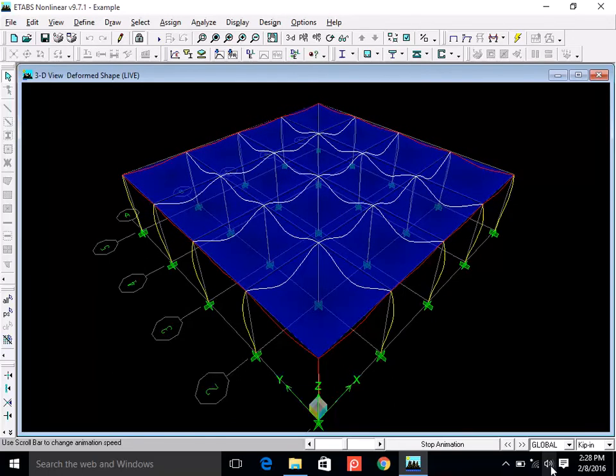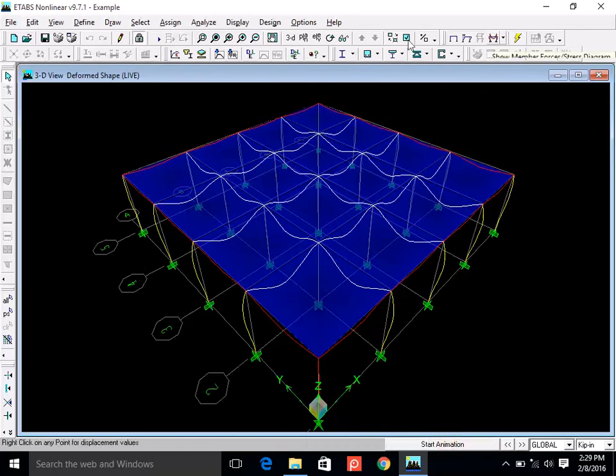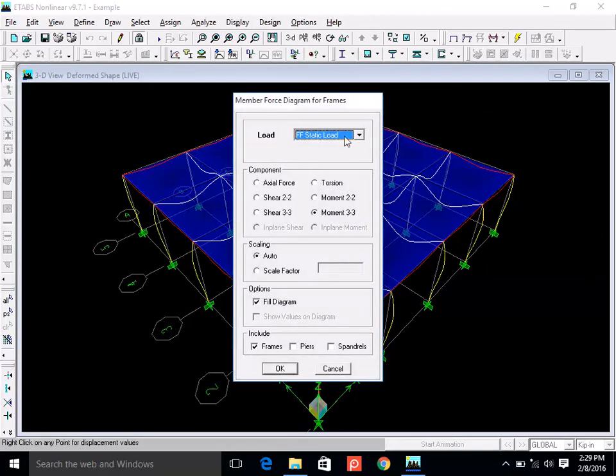in this case, okay, if you come here or maybe here, display, show deform or show member forces, and if you look at the frame forces, which is actually beam or column, and you see for live load, if you see bending moment, what bending moment? Oh, I rubbed it. For the beam, which bending moment? It's about 300. Yes, sir. So I see M33.